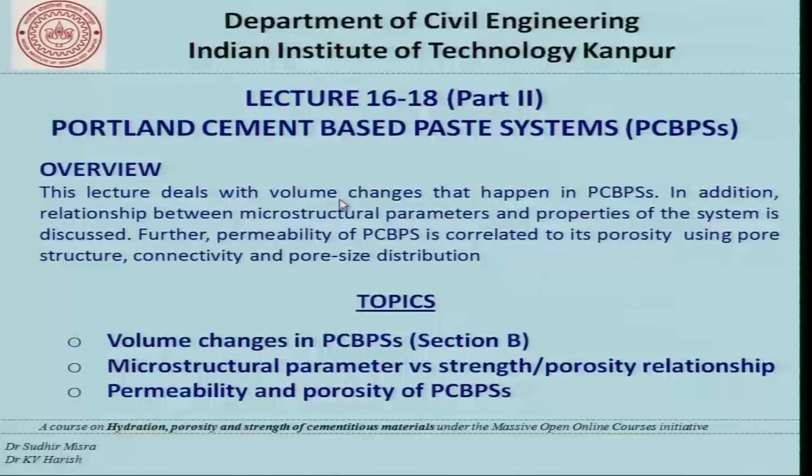This lecture deals with volume changes that happen in Portland cement based paste systems. In addition, the relationship between microstructural parameters and properties of the system is discussed. Further, the permeability of Portland cement based paste systems is correlated to its porosity using parameters like pore structure, connectivity and pore size distribution.